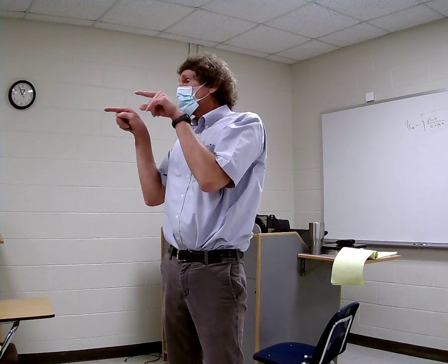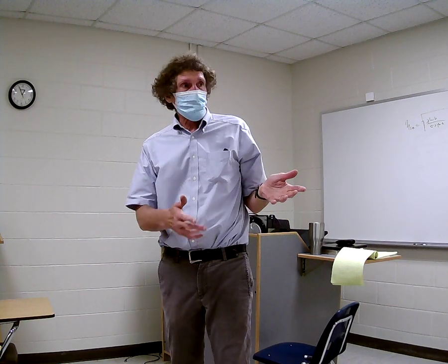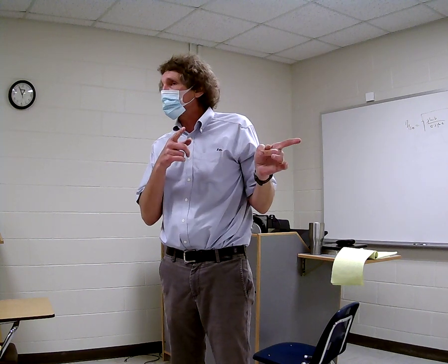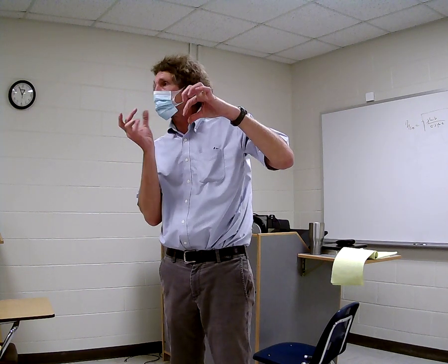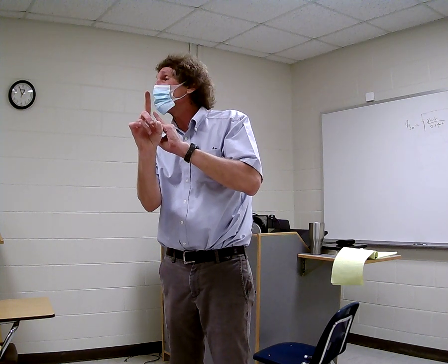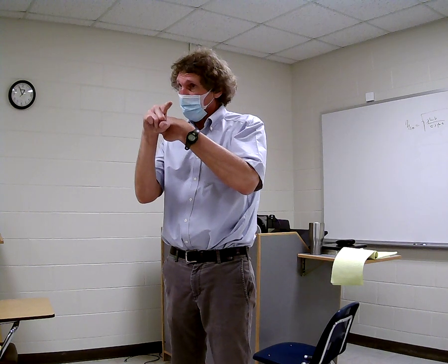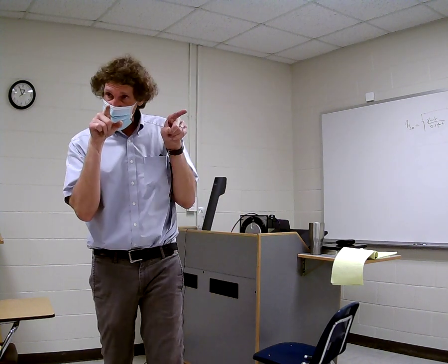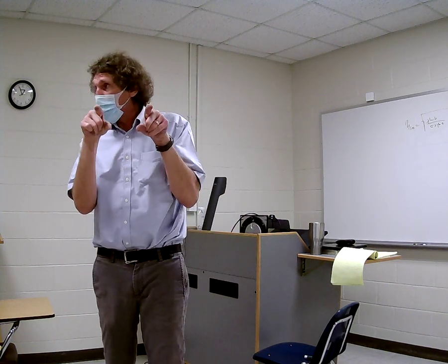Almost all the things we do, we want differential voltages. Like a transmission line has a plus minus voltage, current goes in opposite directions, right? That's called a differential mode. The current is going in a different direction in two wires. Common mode means the current's in the same direction. Now you don't want that, but here's how come you get it.